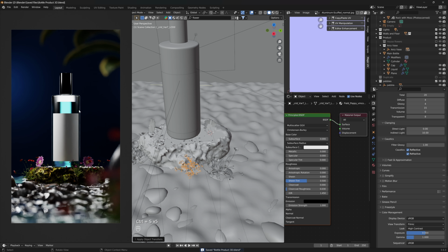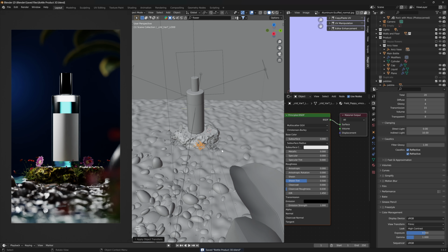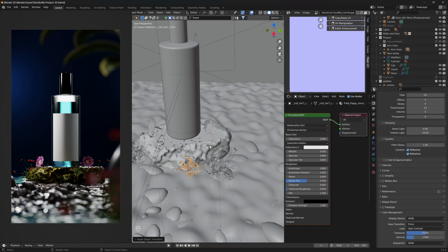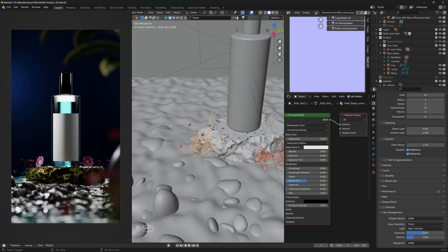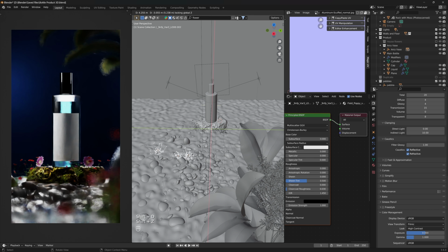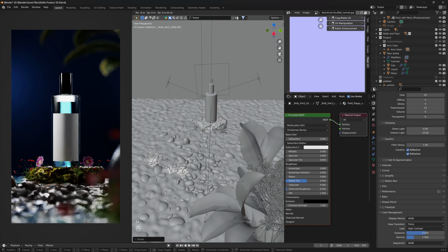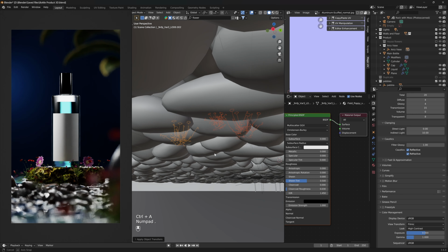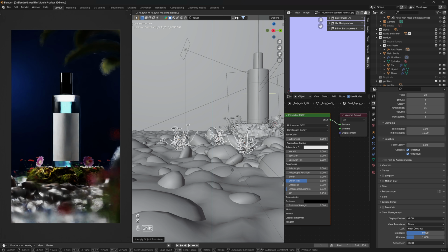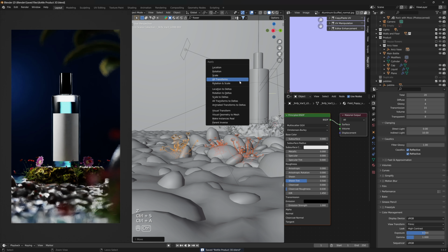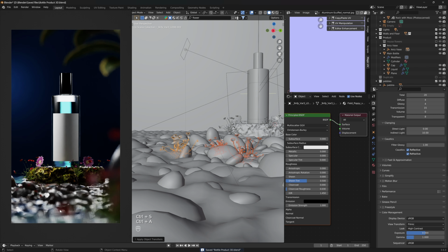Now this is looking like we have created an environment. Okay, so it's looking good. And then selecting these three, then Shift D, Shift C, putting them randomly over here and there, just to cover them. R Z, yeah, so something like this. G Shift C, and then scaling them down more. Yeah, that is looking fine. And G Z, putting them down. So something like this, so that we have some tidbits over here and there.